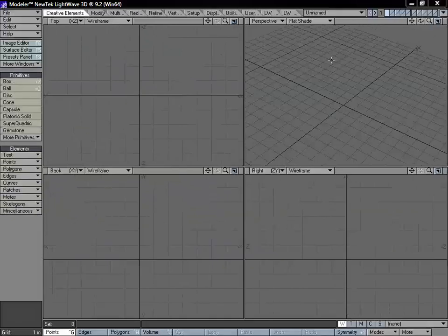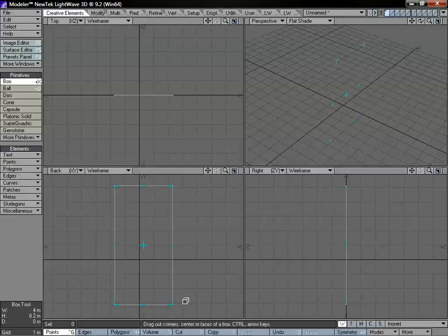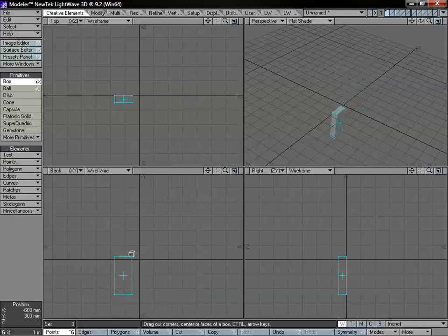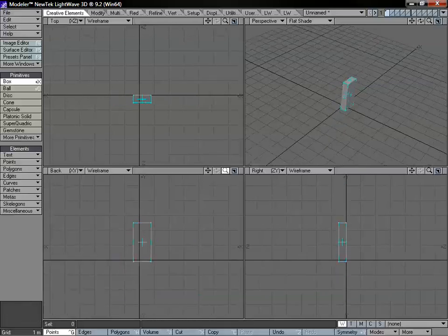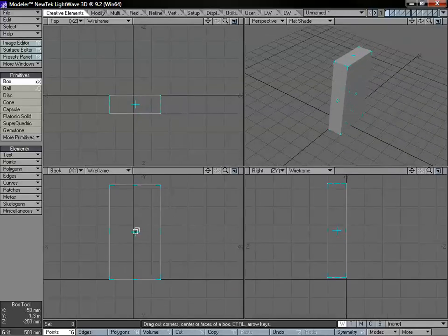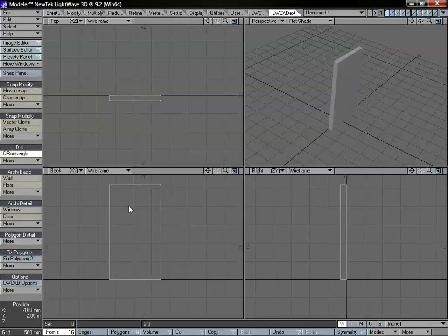And now we're going to take a look at creating custom windows and doors, and also fence objects. So I'm going to start out just by creating a box. We're going to create a window. And I'm just going to size this down so it's not a gigantic window. And then I'm going to switch over to the drill options and just use D-rectangle.